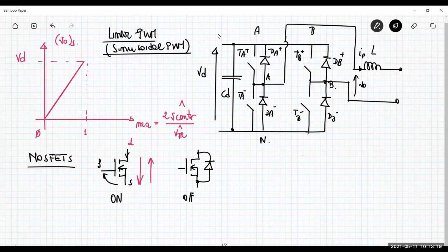Of course, this diode is not designed to be a diode, it is something that you have for free in the construction of the MOSFET. So maybe this is not optimized for fast operation. But anyway, you can use this body diode, for example, for conducting a current in this direction when the MOSFET is off.